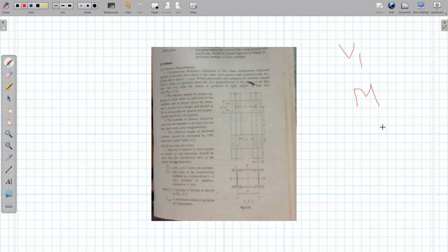Then direct force divided by the rivet value will give you the number of rivets required. Now increase it by 3 times, right? That's what we need. Then you calculate the force due to the moment at the farthest rivets.